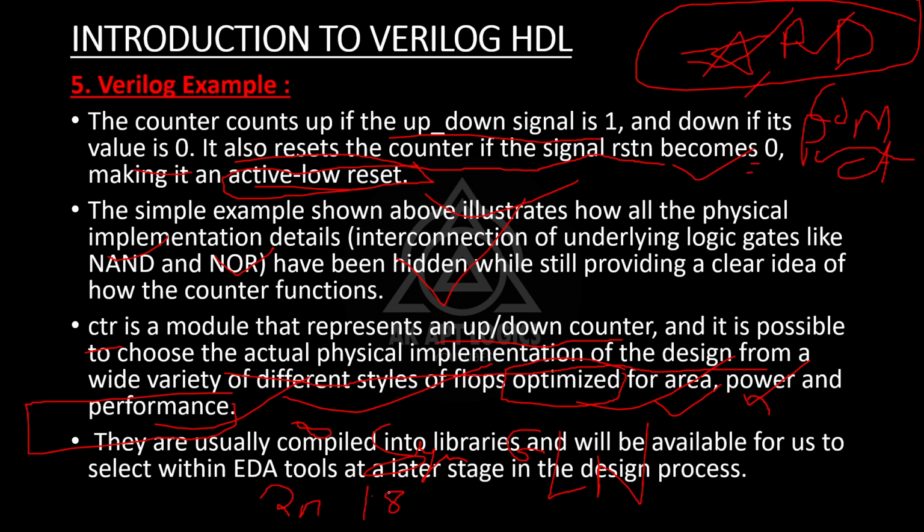In those files, we already have the predefined shapes and symbols of the design, and the size of our NMOS and PMOS in 180 nanometer technology. Those are predefined. So we will use those, design a circuit, and test it. After completion of our design code, if the design code is correct, it will be taken to the backend.